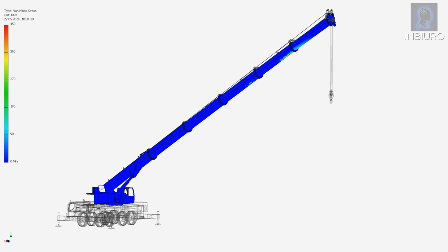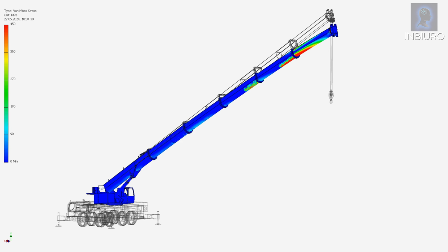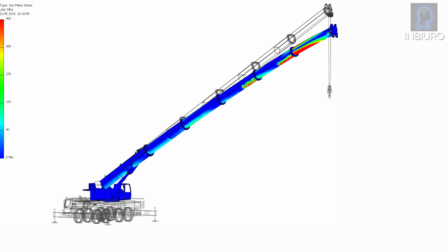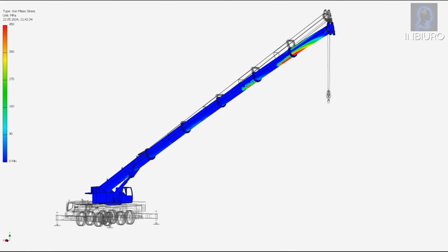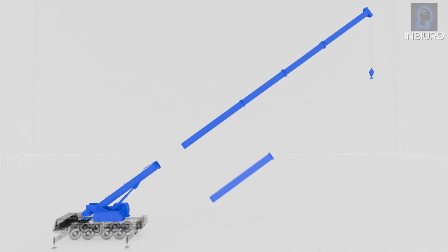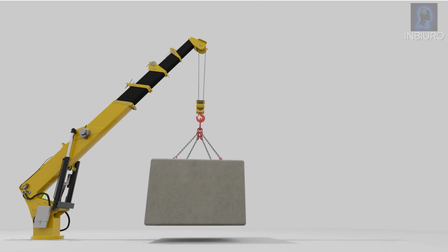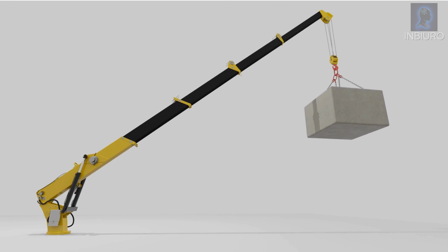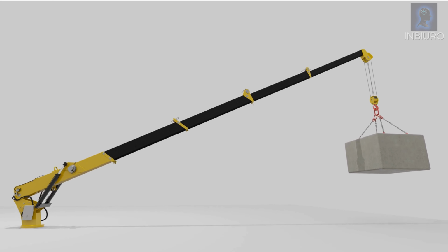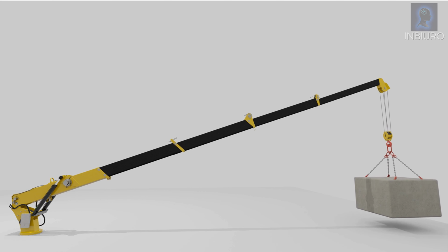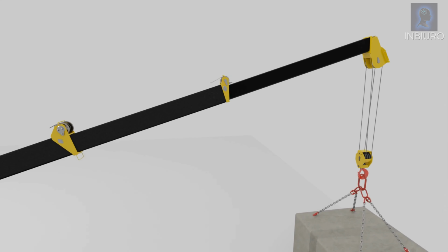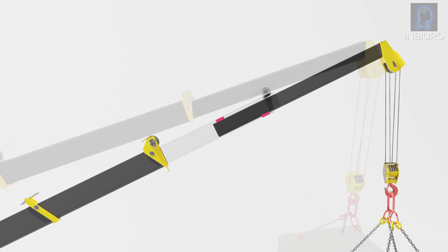Running FEA on the entire structure takes hours of computation, which often fails due to bonding errors or provides inaccurate results because of very coarse mesh. Another reason for avoiding this method is that any change in part of the model costs you recalculating the entire structure. We can make it more efficient and more accurate by combining analytical methods for the structure and running FEA on individual elements afterwards. Why don't you try this?